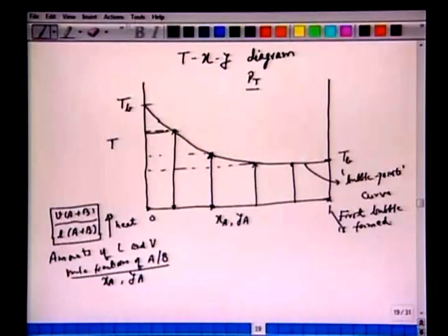All right. So this is the temperature at which the boiling just starts taking place. If we further heat it, then we will see a very significant amount of vapor is formed. In other words, now we will have two phases: one vapor containing A plus B, and another phase, the liquid containing A plus B also. In this case, the amount of liquid and vapor will be different. One can measure this amount of liquid and vapor.